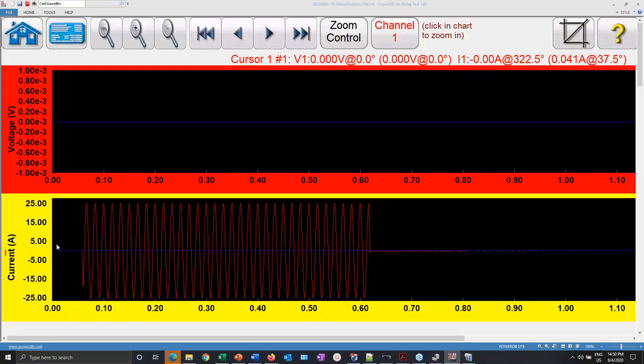Now I'm going to show you what the event looks like, and this is what I'm going to play back into the relay. This is a tool that's used, I would say, in forensic analysis. When I say forensic analysis, I may be taking a name from the movies or from another domain, but a lot of times you have a failure or a fault in the system, and you have to play back the events that resulted from that failure to figure out if the relays that were involved in the fault acted correctly.